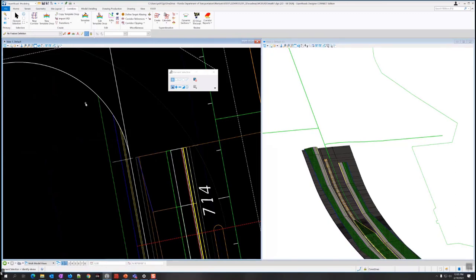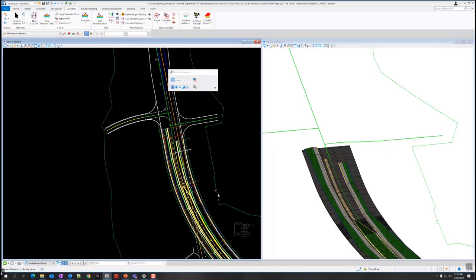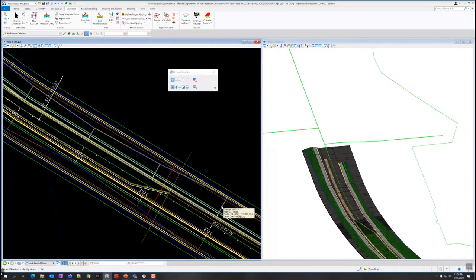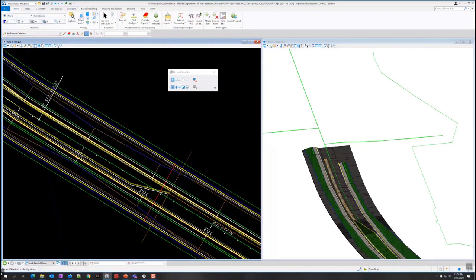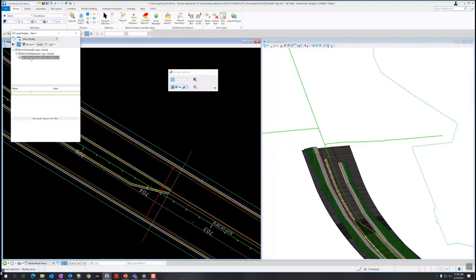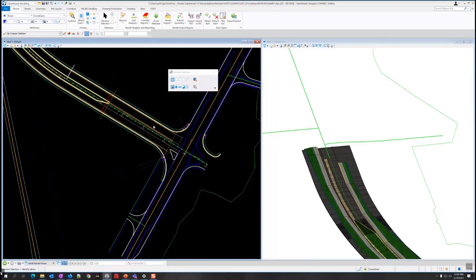So the next exercise, we're going to go ahead and move this over with a point control. So that's exercise 2.10. The command we need for this is going to be, hold on a second here. This is getting cluttered. I'm going to turn off the level display like we did on the other one. So I'm going to level display manager, and I'm just going to turn off the default 3D, right click and do display. So it's a little bit cleaner in here.